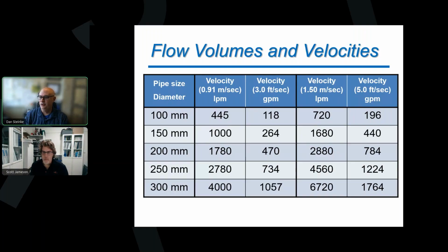Brent asks, how do you know how much excess chlorine to add to the distribution system before flushing? That one you're going to have to use your best guess. It might be one of those where you say, okay, this is what I thought it was going to be, and then we measured it out in the field and there was way more demand by what we stirred up, and we're going to have to adjust this for the next time. I usually try to recommend that people go up by about 0.5 milligrams per liter above what they normally have in their system as a good starting point. But you kind of just have to take your best guess and see how it works for you.